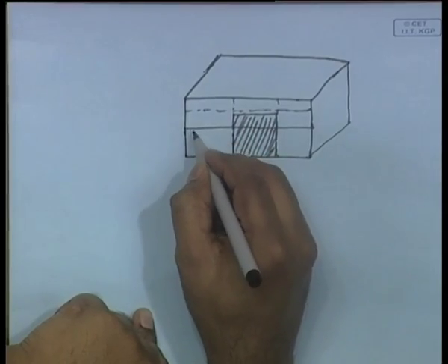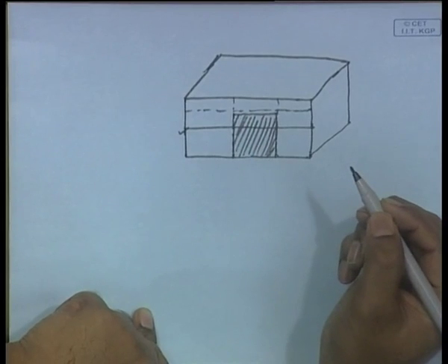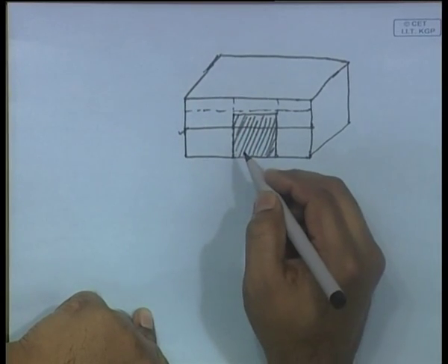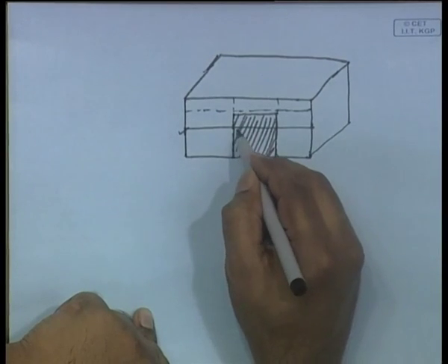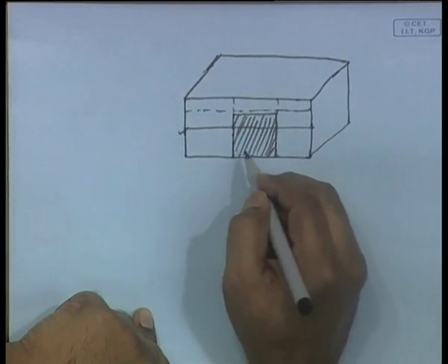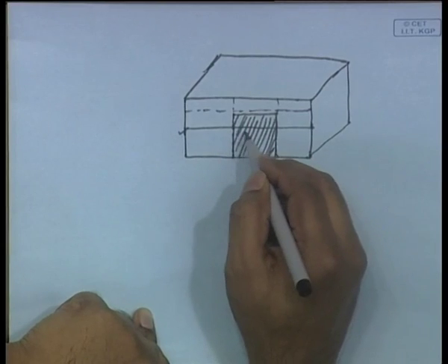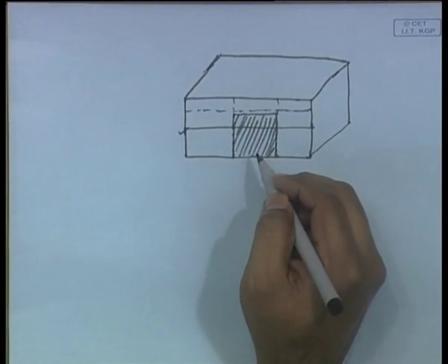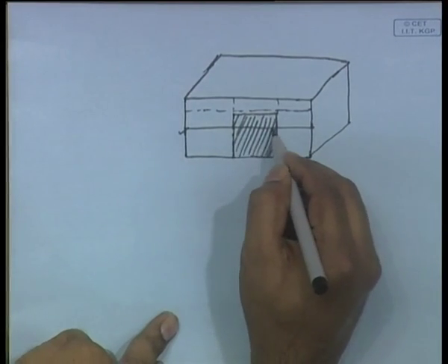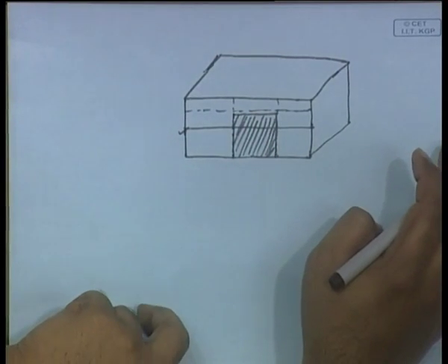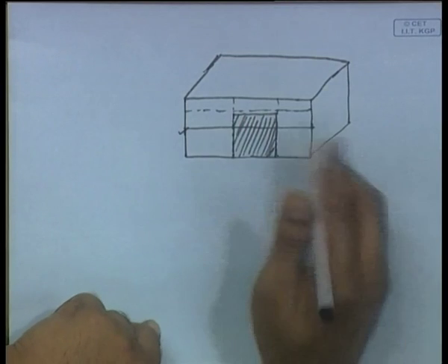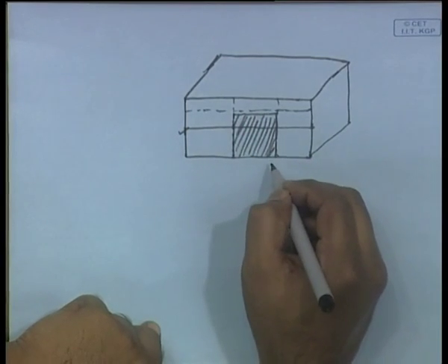So there are two possibilities, as you can see. In the first case, the draft is below the flat. In that case, the problem becomes just like what we have done so far, the problems where you had some compartment bilged and that whole compartment's buoyancy is lost, that volume is lost. So it becomes exactly like that.